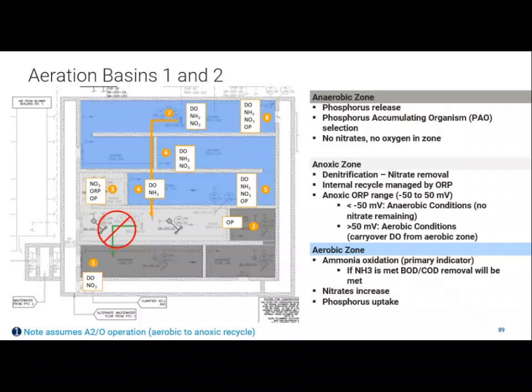Then they went through the anaerobic conditions and then measured OP, orthophosphate, so soluble phosphorus. Why did they measure soluble phosphorus at the end of the anaerobic zone? Exactly, you're making sure that PHA is being stored and the phosphorus is being released.